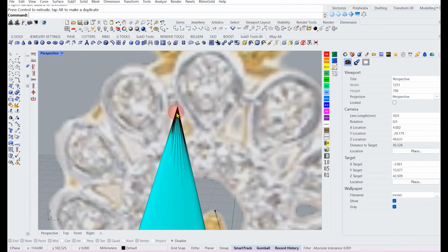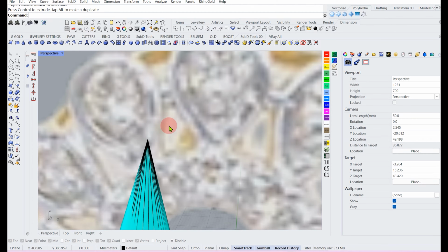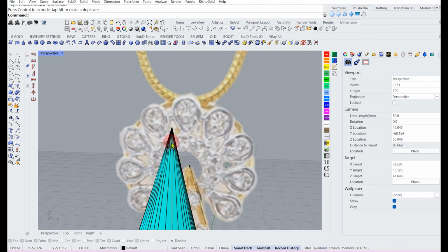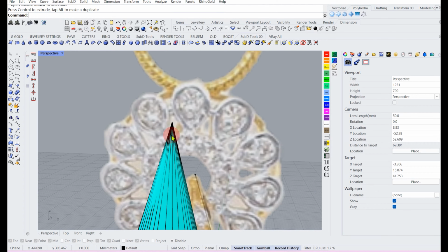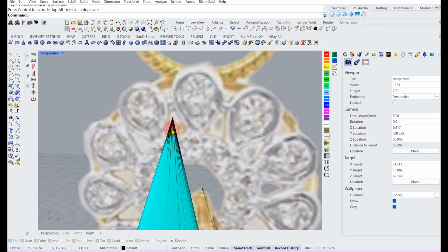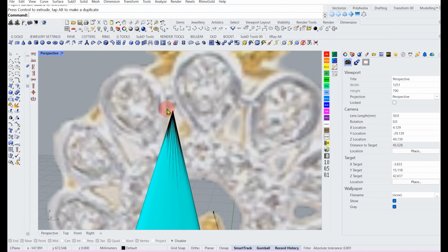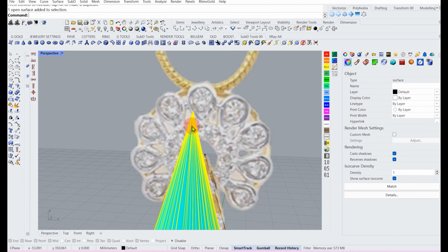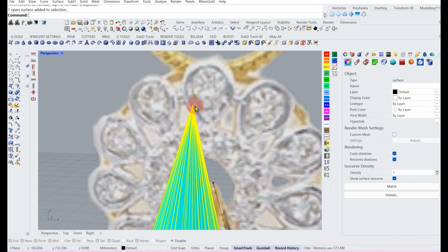As you can see, the sharp tip over here is not good for creating geometry, solid geometry. It causes naked edges or bad object. If we offset the surface, it will create a bad object.